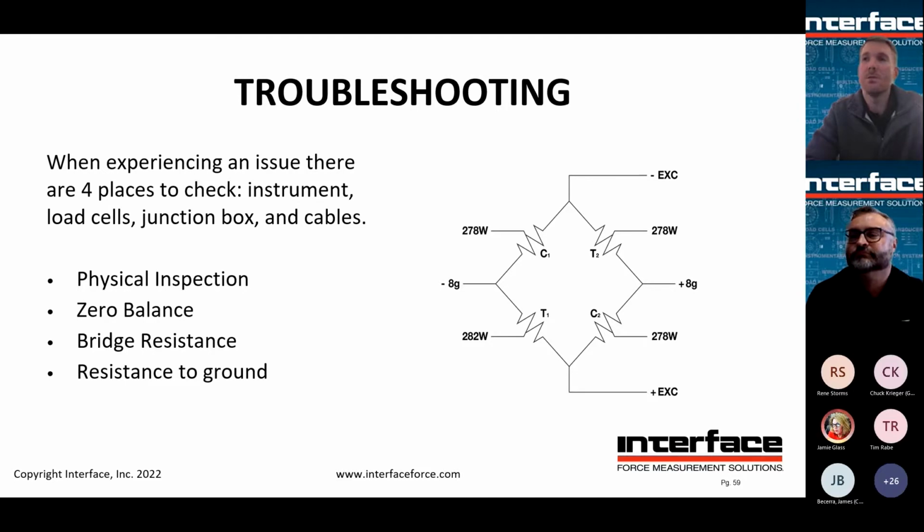As Keith was mentioning before, using a simulator will help you determine if the issue is in the indicator. That will pretty much tell you, hey, if you use a simulator, my scale is good. And if you're still experiencing issues, you know that the problem is within the indicator. Now, if you hook up your simulator and your indicator and all is well, then you start looking at the